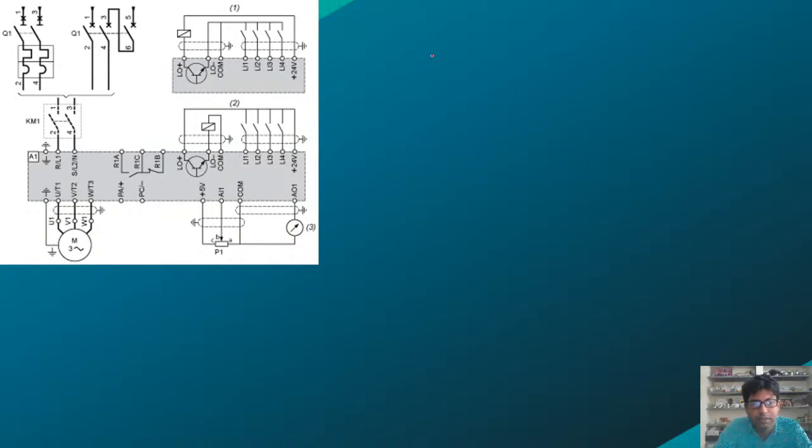You can take a contact. I will be using a 2-wire connection, so I will be using these 2 contacts. This contact name I am giving forward, and this contact I am giving reverse. Now, operator by mistake should not press both. If he presses both, then it should not operate. I have to make that simple protection.